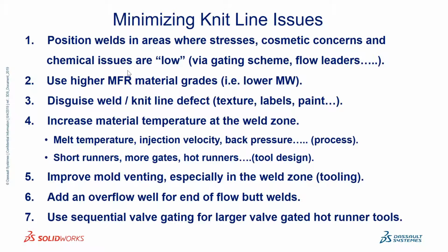So what we're ultimately trying to do here is figure out what we can do to minimize this issue with welds, whether it be the structural, the visual, or the chemical resistance. The very first and most obvious thing is to try to put the welds in locations where they're the least harmful, right? In terms of cosmetics, in terms of stresses, this is where mold filling simulations are invaluable. It is the combination of the gating scheme and the geometry of the part that will determine the locations of the knit lines.